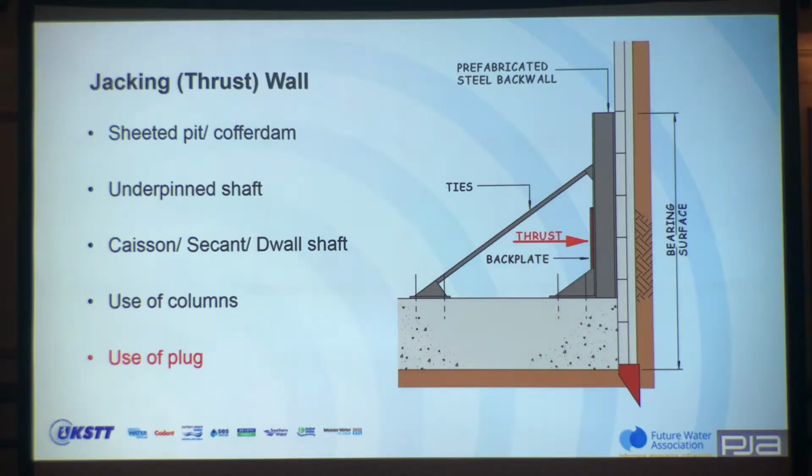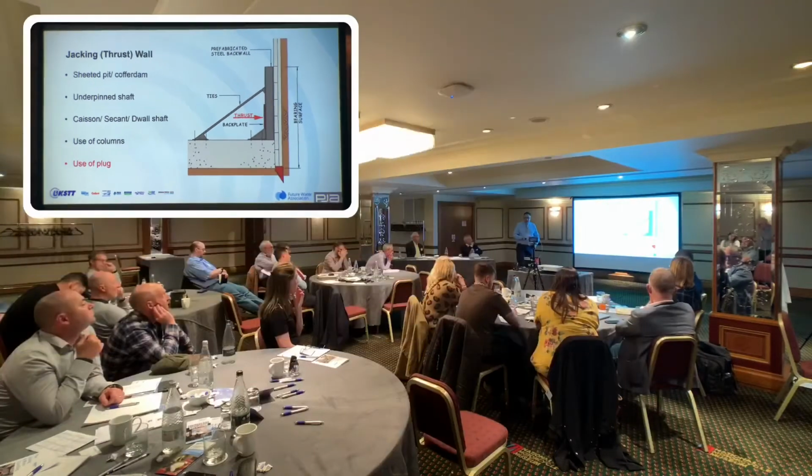I've done this several times. One of the problems that you do have, in this instance, is that it's almost a combined effect, because if you consider that you'd be pushing onto there, these would be doing an awful lot of work. You're relying on the bolts then to really take the load, in shear almost. In this instance, you'd have some benefit from the back wall if you were pushing there.